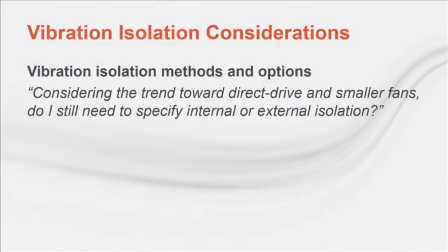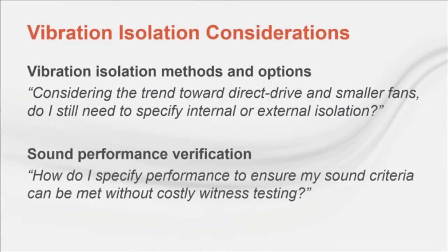In addition to whether and which isolation method to choose, the ultimate consideration should be performance, specifically sound performance, as inadequate vibration isolation can generate noise. To help make the best decision on which isolation method to choose, be sure to request quality sound data taken in accordance with AHRI Standard 260. Then simply compare the unit sound power levels with the job requirements.